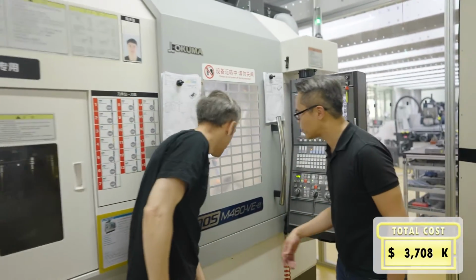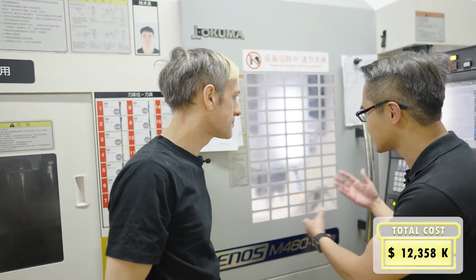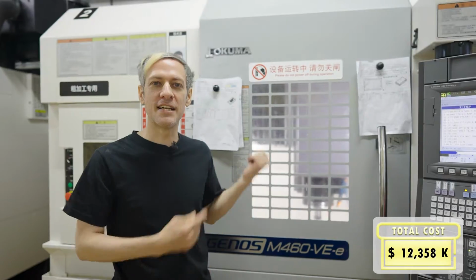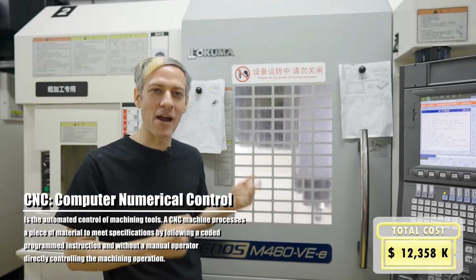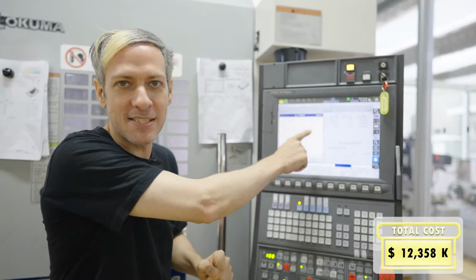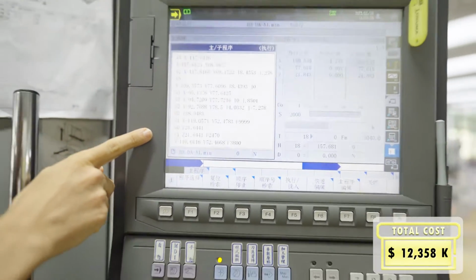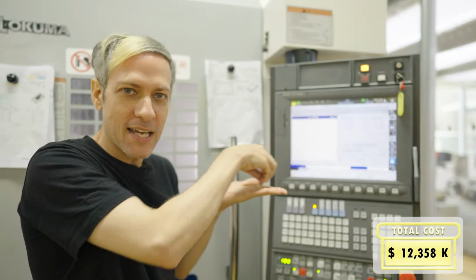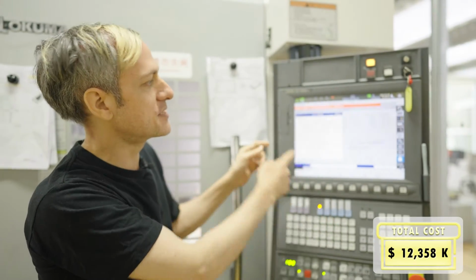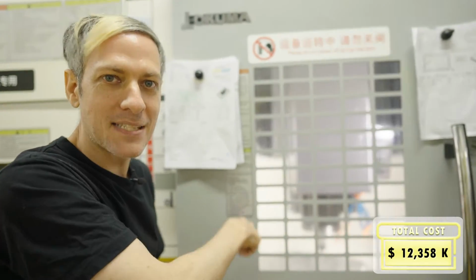So here is our rough milling to do the heavy job. This machine will cut the excess material, but just really roughly. So this is a CNC machine, which stands for computer numerically controlled machining. And what happens is, when they design the tool paths, it creates something called G code. It's called G code because all the commands start with a G, and these are basically the coordinates for each movement. So all those files were created in the CAM, and now this machine receives the file and steps through each step, and then moves the cutting tool based on the program.